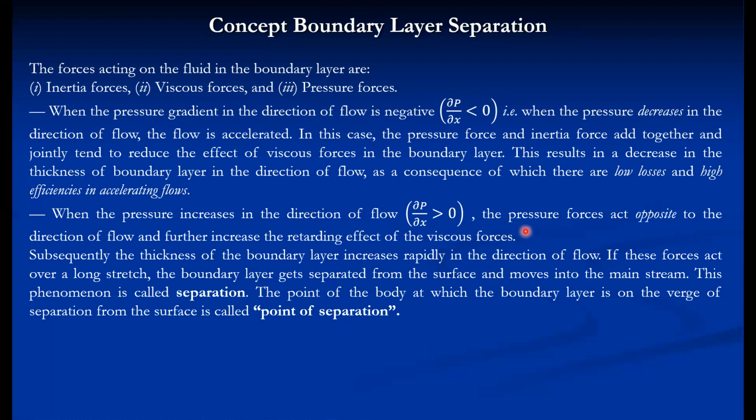So what will happen? The pressure forces act opposite to the direction of flow and further increase the retarding effect of the viscous force. So both viscous forces and pressure forces retard the motion. And subsequently, the thickness of the boundary layer increases rapidly in the direction of flow.